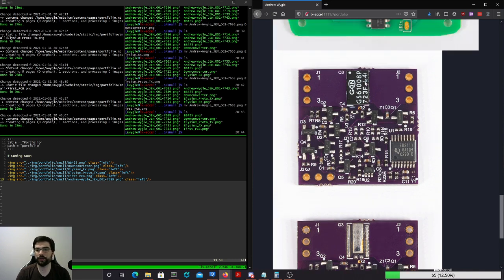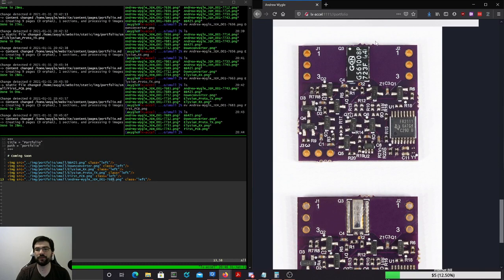The thing about GaN FETs, though, is that for a long time they were only available in depletion mode, which doesn't work really well for power switch type applications. So the new innovation is enhancement mode GaN FETs, or eGaN FETs. And so those are great, but the problem is that they're only NFETs. I said PFET controller. That's wrong. NFET controller.